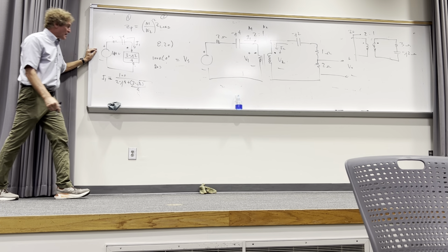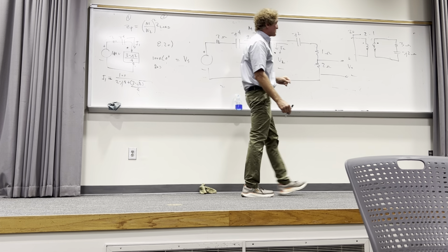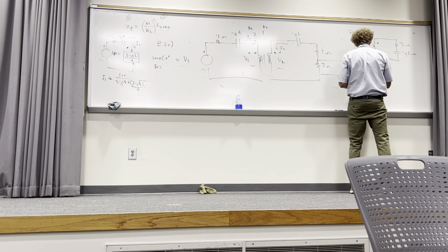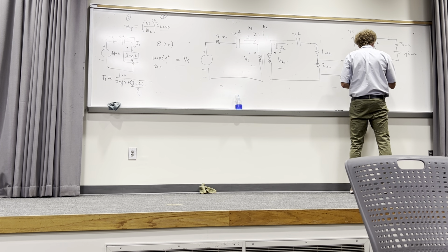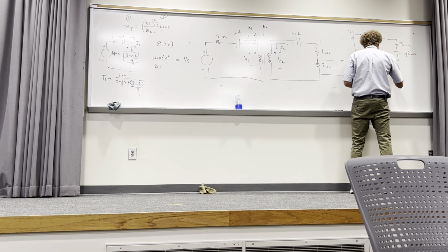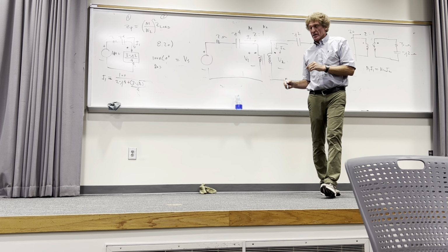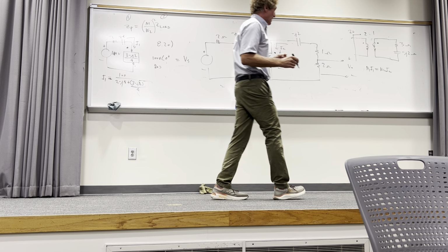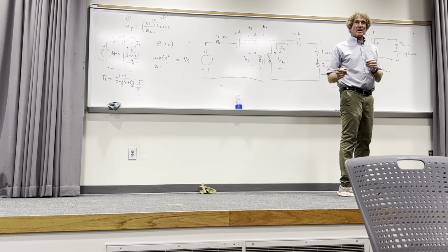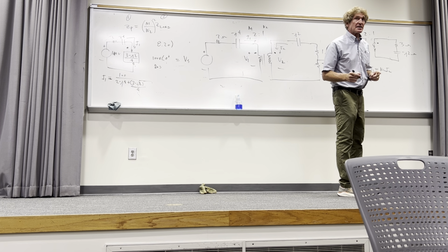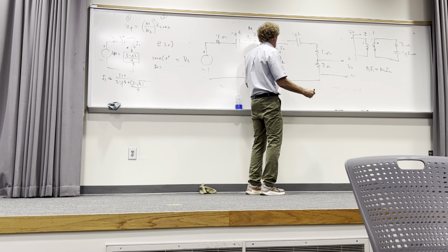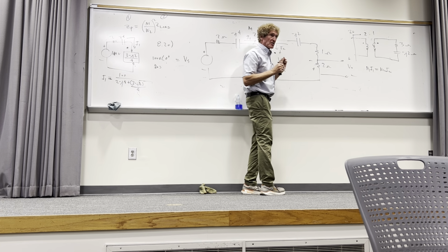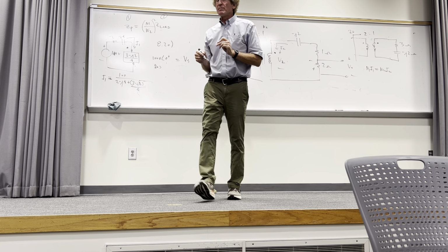Now, once you have the primary current, the relationship to the secondary current, here's I1, here's I2, it is this: N1 times I1 is N2 times I2. If you write that down and understand it, you will not make mistakes. So we want I2, because if I have I2, flowing this way, I automatically have this voltage right there, don't I? 2 ohms times I2 would be that voltage.